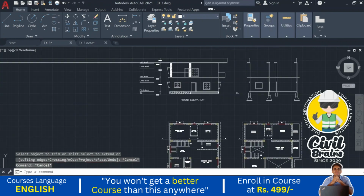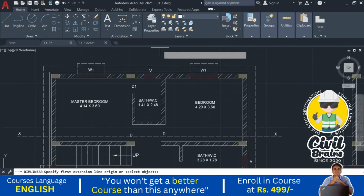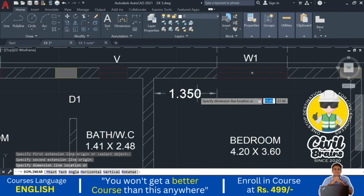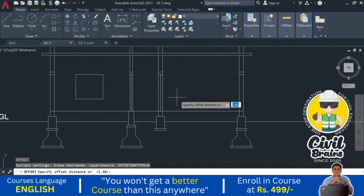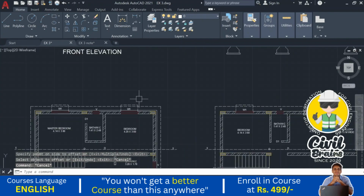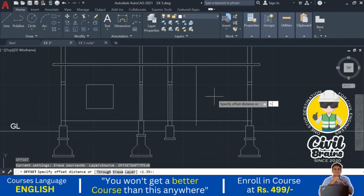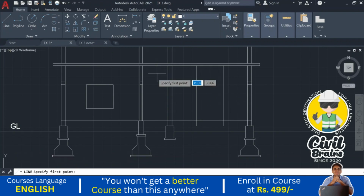So this is the one window which is visible here, and one more window here that I just measure, 1.35. Offset 1.35 from here, and the width is W1 only, so 1.5 meter, offset 1.5, press enter. Okay, this level is the same.